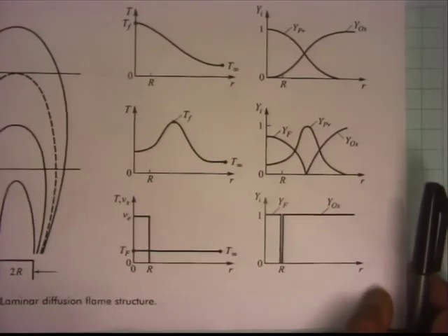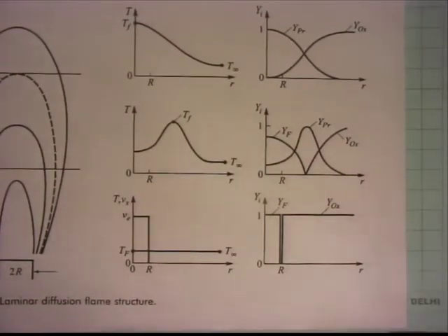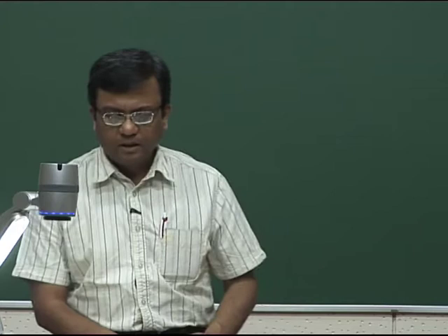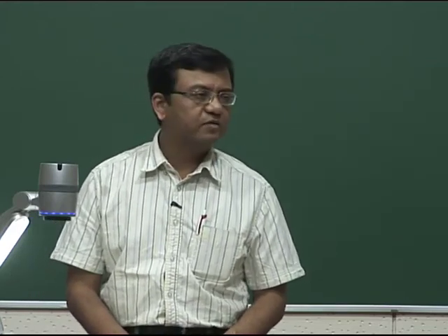So in premix flame, maybe I'm wrong. In premix flame, the shortest flame length we got when it is in stoichiometry. Is it correct? I mean, I've seen somewhere. Yeah. So, the question is about when do we get a shortest flame length when we have premixed combustion, right?